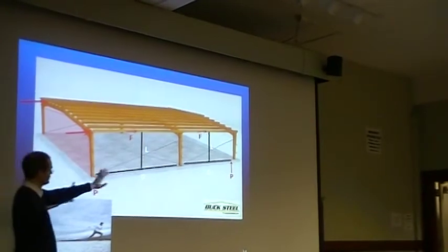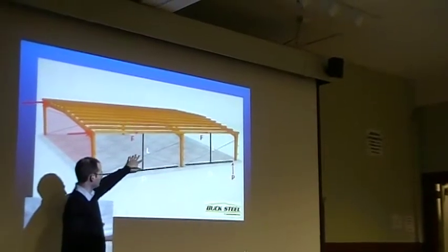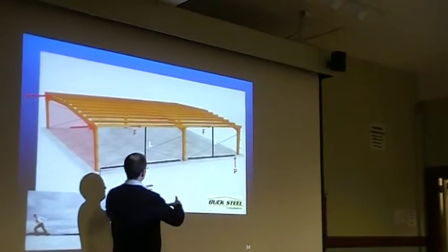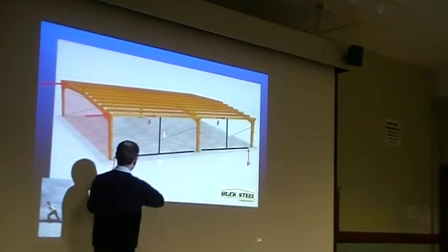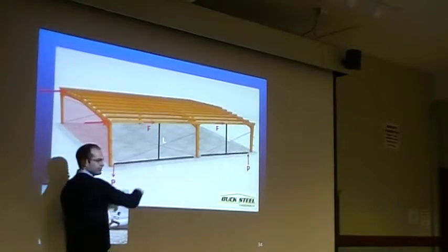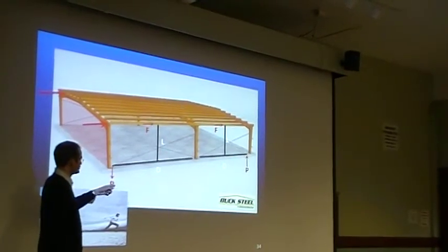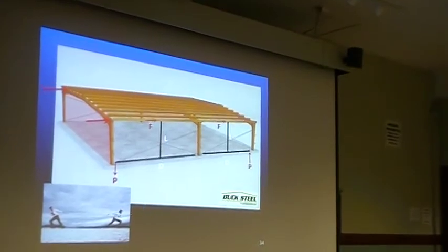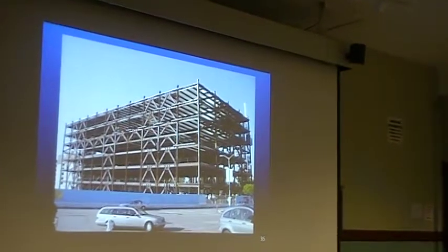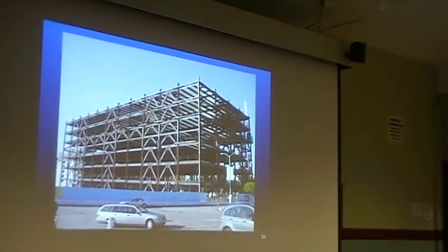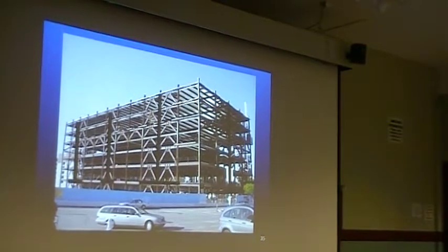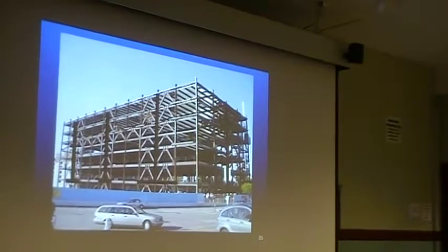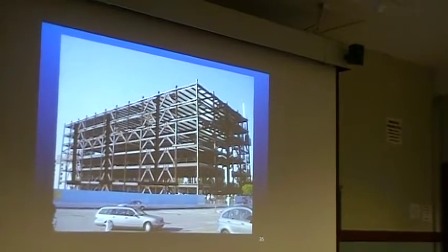And we can see that if you had one brace frame here, you had your pushes and pulls here, two braces next to it, you're almost forming one really long beam happening here. So just by manipulating these relationships, you can frame out a building real quick. Another steel frame building, same thing. You see these complicated brace frames, but really all you're asking it to do is to cantilever up from the ground to keep the thing from swaying over in the wind.